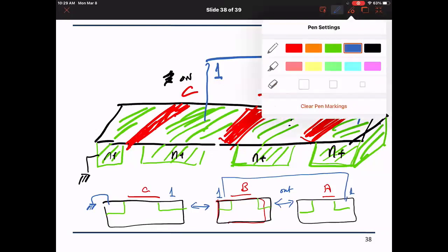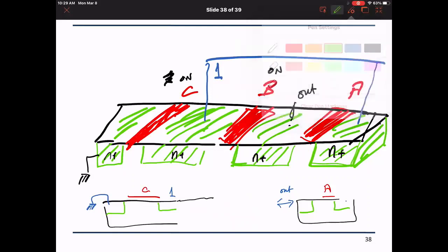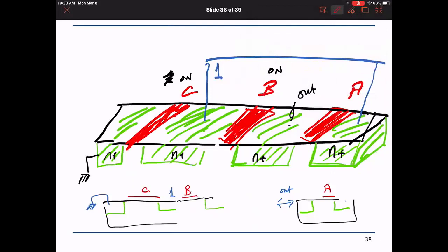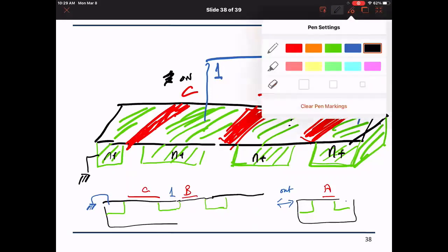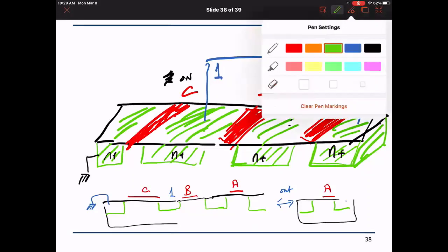Okay, now how do we have them in this example is as follows. Instead of B being far away, B came next to it with the same diffusion, so B sits here and we made a separate diffusion for it. Okay, and this is the diffusion around B. And then we continued with the substrate and we really drew A here. And then we drew the diffusion around A. This is what we mean by the stick diagram, right?